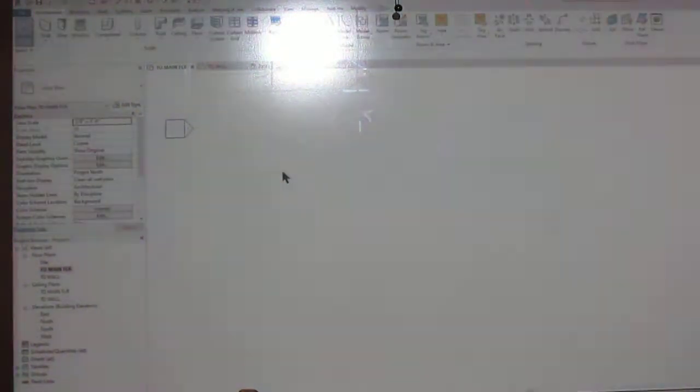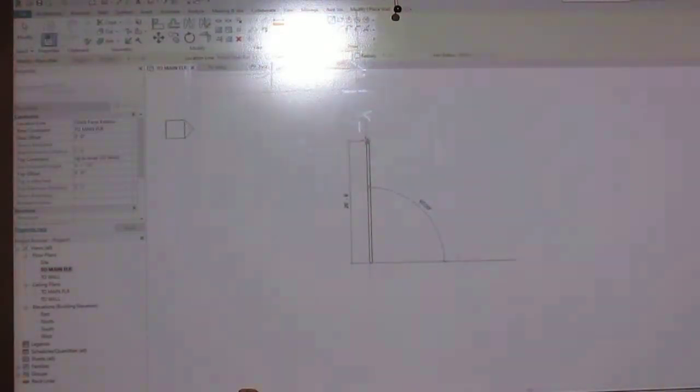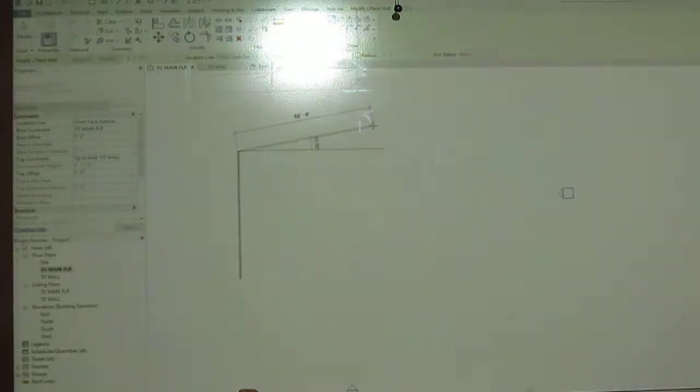Yeah, darn it, sorry. Wall, still got everything, got to get the top constraint back. I told you one thing wrong. So we're going to click it, come up, and it should be in that mode, so I'm going to hit 48 feet and hit enter. Do you have to hit feet? Yep, you do. And so you should now have a dual line that's 48 feet long.